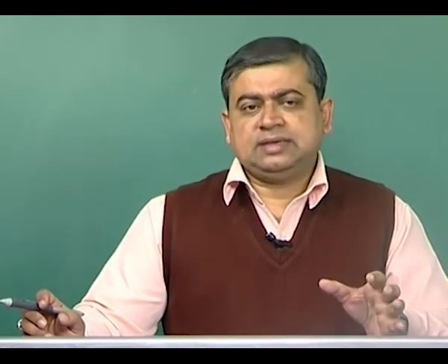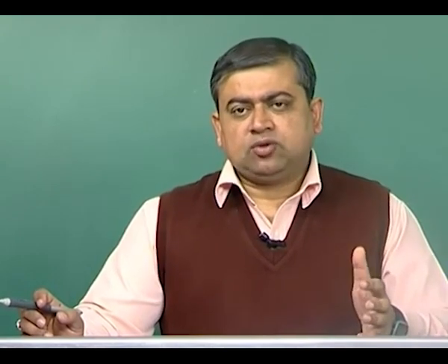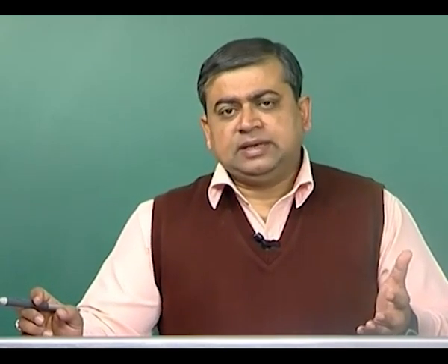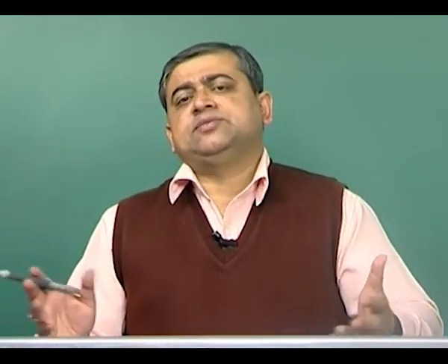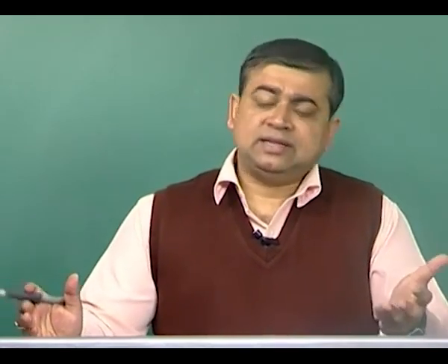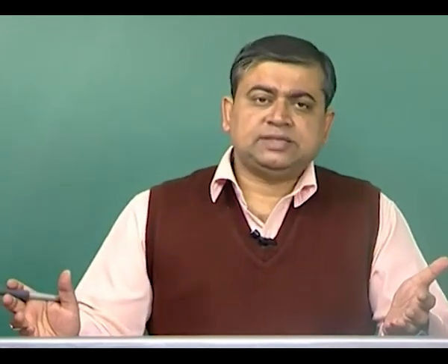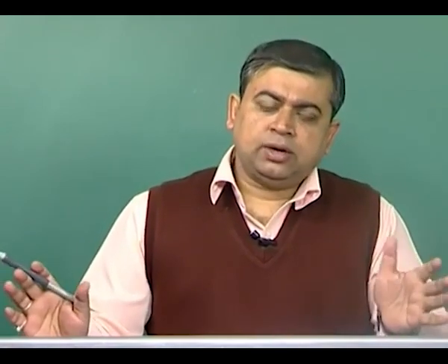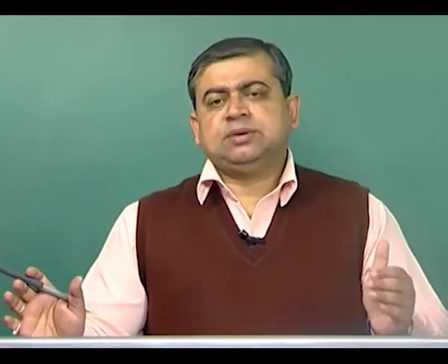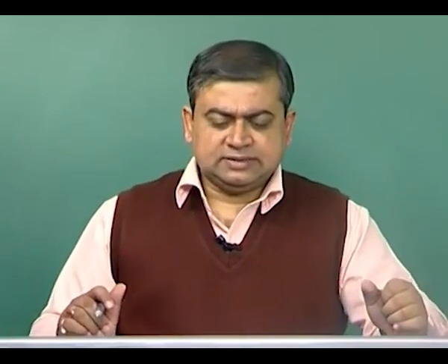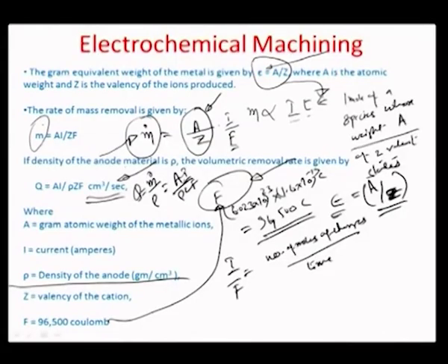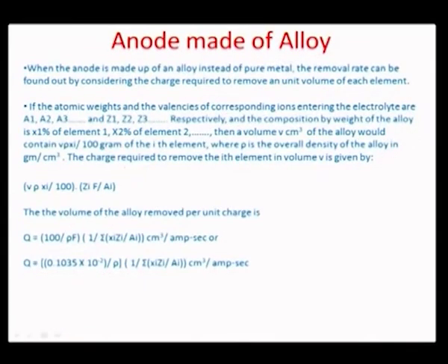And so, therefore, this extension of this electrochemical basis of material removal has to be applied to an alloyed system as well, where there is not a single phase as one metal, but a variety of phases in mixture with each other. So, you will have different atomic weights of these phases, you will have different densities of these phases which are in dissolution, and therefore, a complex system emerges because of the application of this straightforward single metal case into that alloyed system. So, let us look at a problem example of that sort as mentioned here.